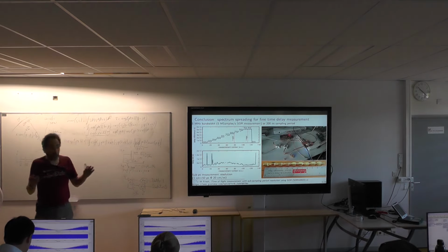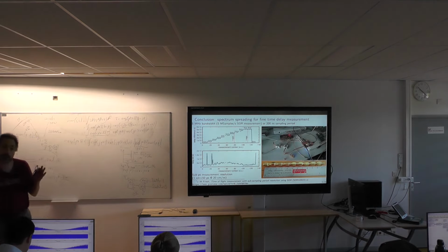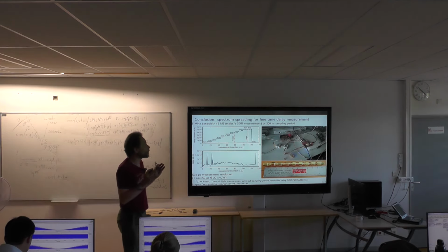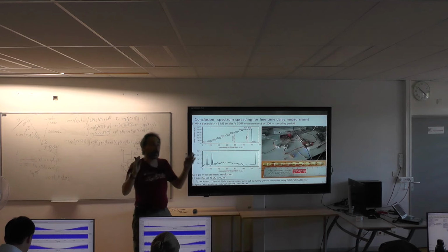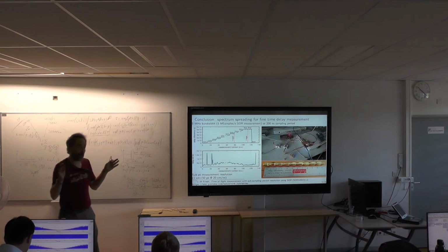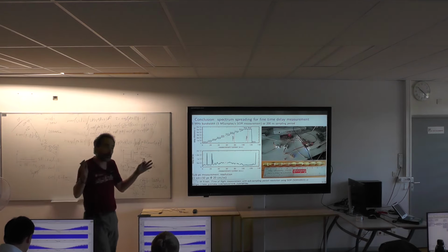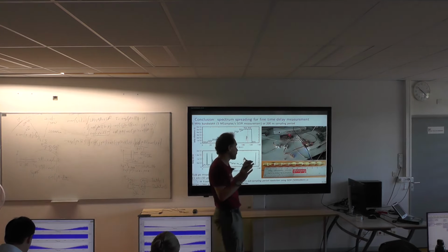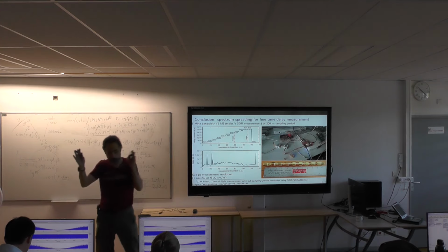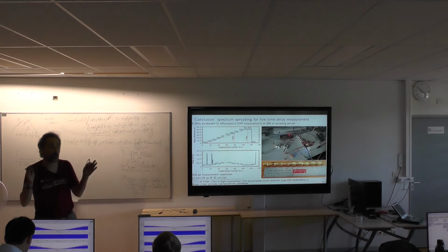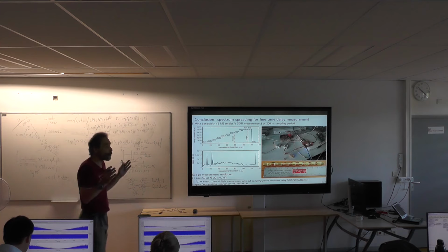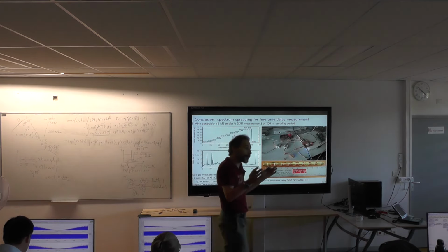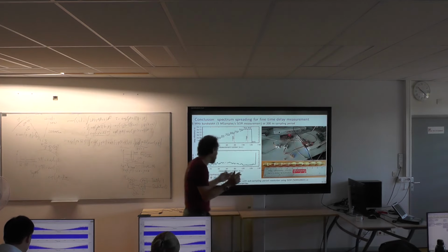And this is something I prepared for our two-way satellite time and frequency transfer experiment. When we're broadcasting two-way time transfer signals, we are allocated 5 megahertz bandwidth on the satellite. If we go above the 5 megahertz, Telstar will call us because we're leaking onto the neighboring channels. So we have 5 megahertz, and 5 megahertz bandwidth is a 200 nanosecond period. So you might say the best you can do is measure the time of flight with 200 nanosecond resolution.